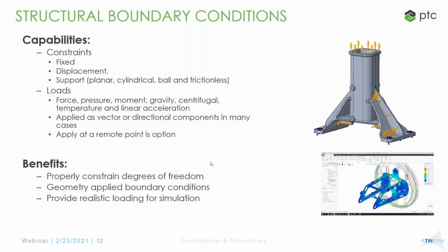You can just say, I want to apply it on a remote point. It's kind of like the total loaded point that we have inside of Creo Simulate, very similar to that. It's very useful when you work on large assemblies again.